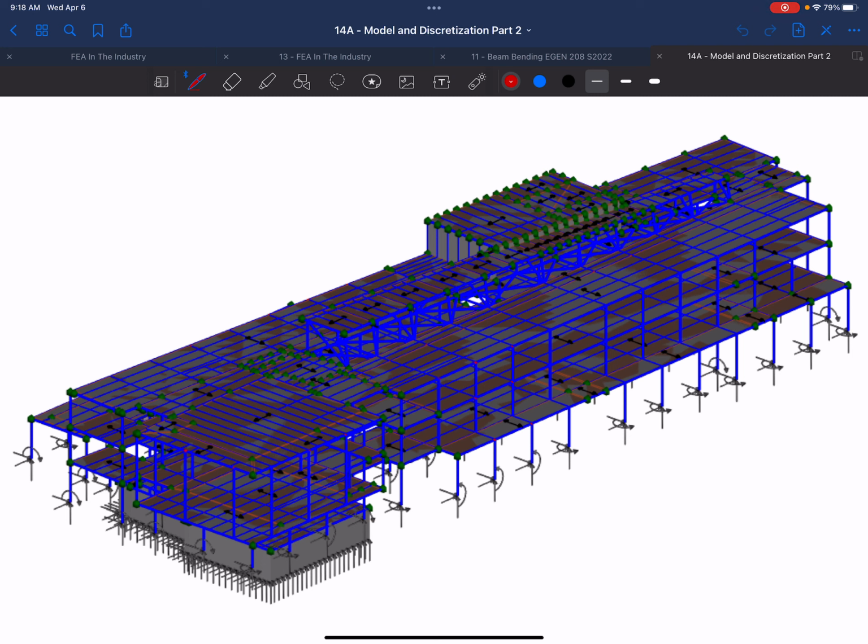And so you end up segmenting these out. You create a nice big key plan that says, okay, this is design group 1 for beams. You'd show that, and then you'd have all these printouts, and you might check a couple to verify the unity values that they get for checking flexure, right? If you went to section F2, you were doing all the flexure checks for beams. There's the yielding, there's lateral torsional buckling in there, all that stuff. Those are verified, and that our model is doing what it should be.